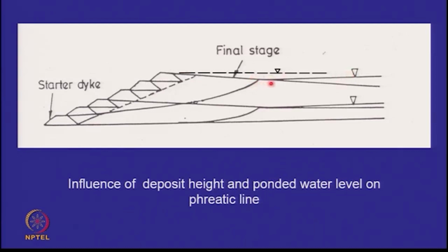I'm still far away, but my pore pressures are now increasing because the water level is becoming higher. However, most of the dams do get operated where the water level reaches half a meter to the crest. When the high pond level occurs, then the phreatic line is formed inside this, and when that happens, it becomes the critical stability issue.